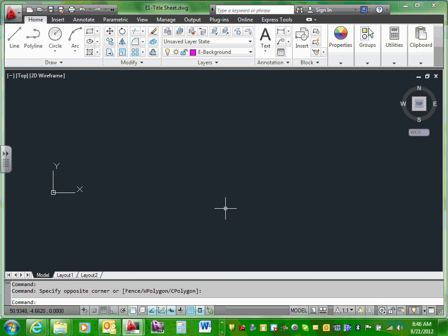Okay, everybody knows what an Xref means. You're looking at a file that other disciplines are working on, and every time you load it, you see exactly what they have changed. Typically architects or mechanical engineers, we Xref them stuff. Okay, so we're going to Xref. When you Xref the background, you always Xref the background in the model space. Always.